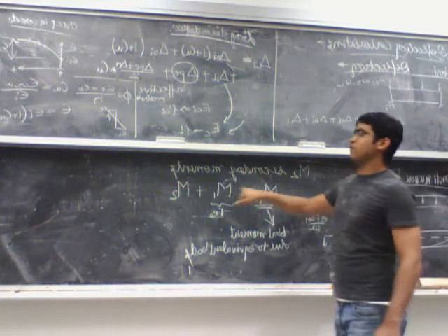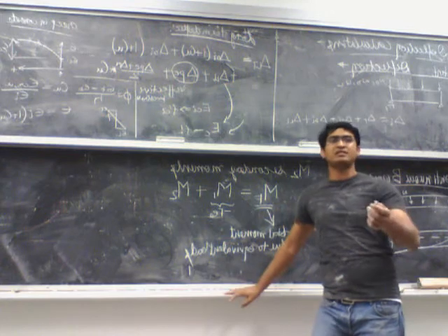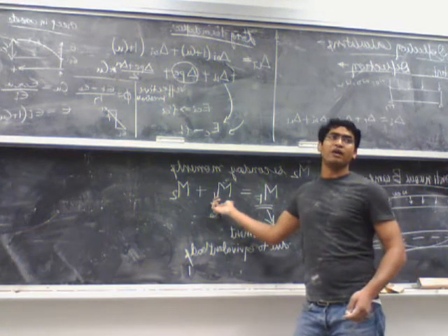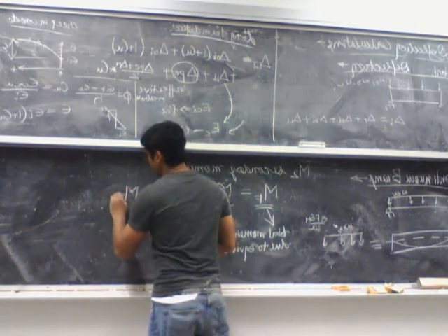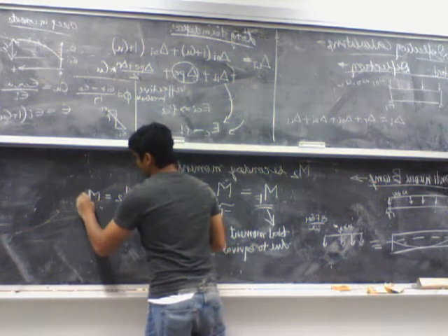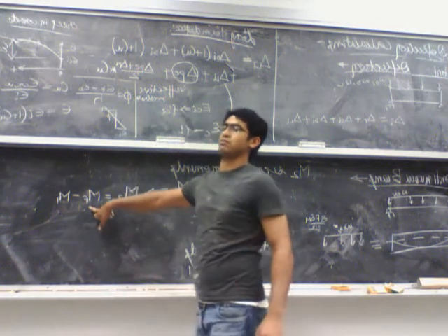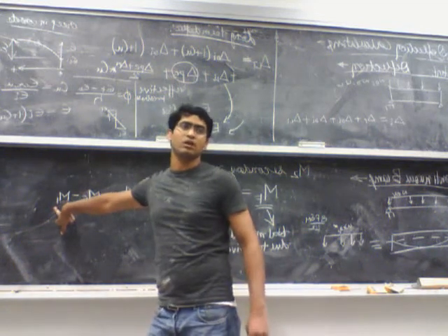Once you have MF, M1 is always minus F times E naught. You know the prestressing force, you know the eccentricity, so you can calculate the value of M1. So my M2 simply becomes MF minus M1. MF you get from analysis, M1 you get by simply minus F times E naught.